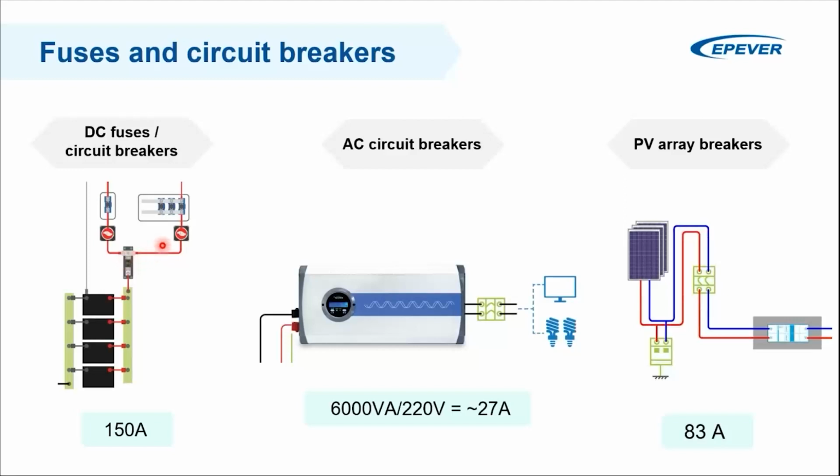And then I know that, okay, my inverter needs to be reset, a fault happened here. But if you do not have individual fuses, you never know what happened, or you at least have to spend some time to troubleshoot and diagnose your system to find the fault. So it's always good to independently connect all the consumers with a dedicated fuse to the batteries for troubleshooting purposes.